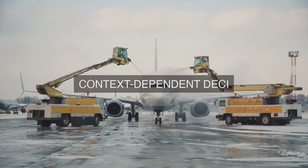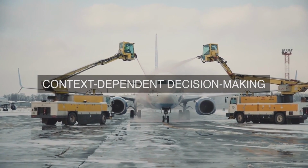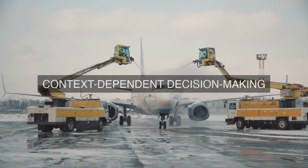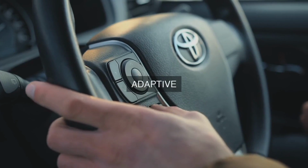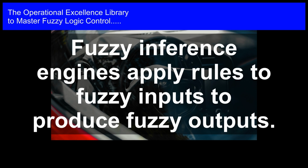Secondly, fuzzy logic control uses membership functions to quantify the degree of membership of an element in a fuzzy set. Membership functions map the input data to a membership value between 0 and 1, indicating the degree to which the input belongs to the fuzzy set. This allows the system to capture the uncertainty and ambiguity in the data, as the membership value can be interpreted as a degree of truth or probability.